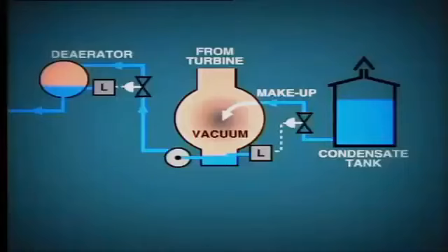When load is increased, the opposite situation takes place, as the boiler water level increases due to swell. In this case, the boiler feed water control valve reduces flow, the de-aerator level tends to rise, so decreasing the de-aerator control valve opening. This causes the hot well level to rise, thus causing the makeup valve to close completely.